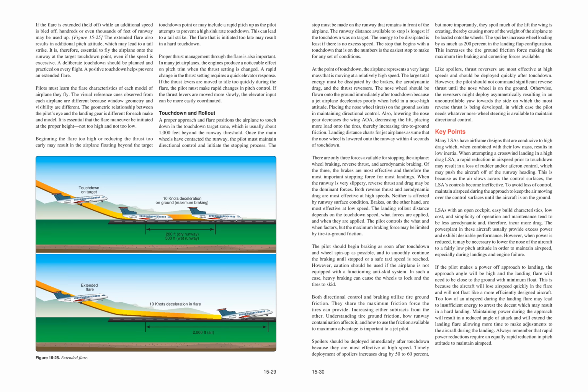Maintaining power during the approach will result in a reduced angle of attack and will extend the landing flare, allowing more time to make adjustments to the aircraft during the landing. Always remember that rapid power reductions require an equally rapid reduction in pitch attitude to maintain airspeed.